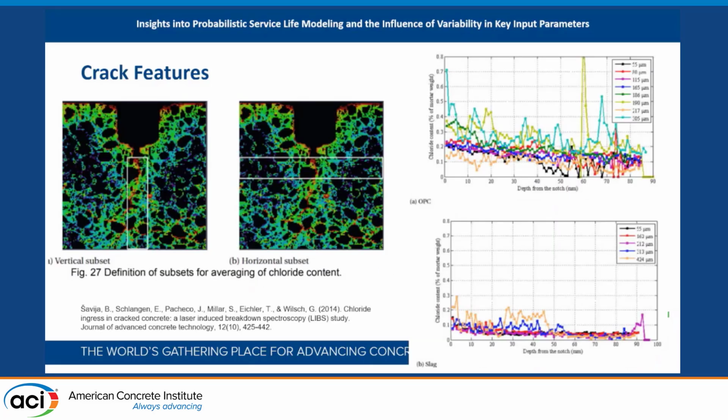These are some photos of analyses that were made on crack specimens, and we inspect them with laser ablation equipment to understand how chlorides transport not only within the cracks but into the concrete, because you cannot determine the chloride content in a crack, right? It's a void, it's a cavity. You cannot extract that and then measure it. Maybe the pore solution there is something you could extract and use, but in practical terms, it becomes really complicated.